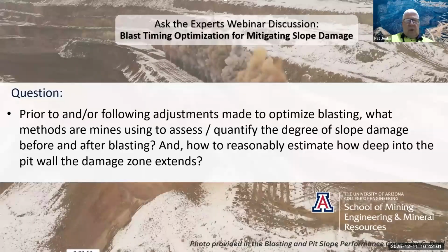Some promising, where core holes were drilled into the high wall prior to mining or during the first phase of mining, and the practitioner took a televiewer tool and measured discontinuities as a function of the depth, and then placed a PVC pipe or something in the hole to preserve it, so that the second phase of mining came.